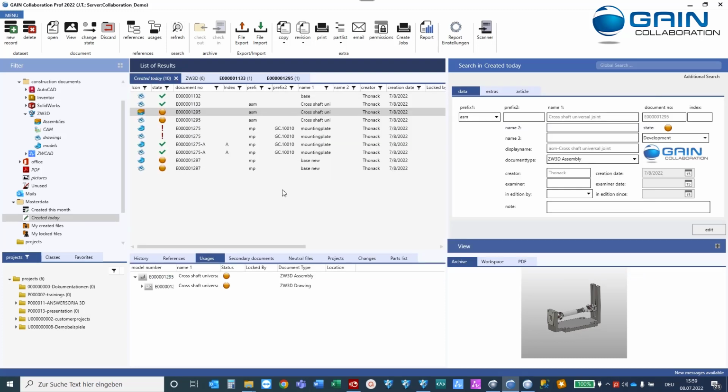And that is actually what I wanted to show in this video. That is, how do I copy assemblies and components? How do I work in the assembly? How do I replace parts in the assembly? Well, either manually, by saying find a new part, pick that, replace that. Or by saying, create a copy of the part directly from the assembly. Then it is replaced. Super simple to use and, yes, comprehensible for everyone.